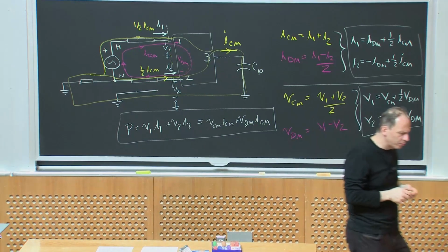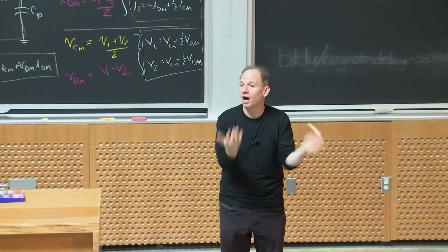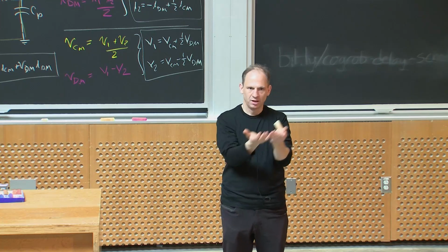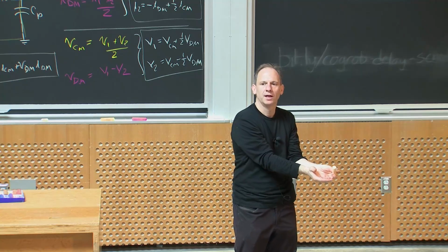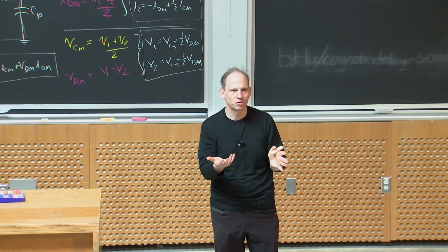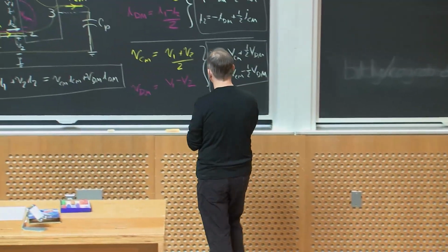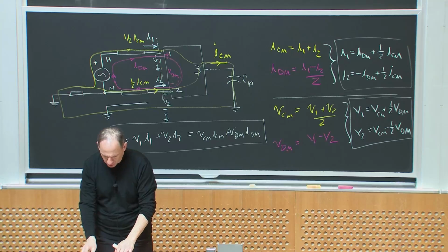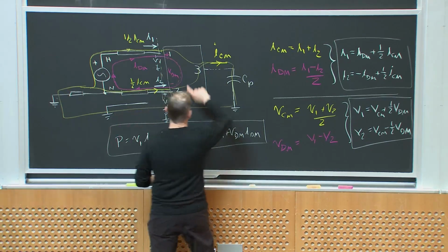But the other reason why people think about this decomposition of voltages and currents is because I tend to use different techniques to fix common mode noise and differential mode noise. Okay? And so decomposing it that way tells you what technique I should use to make a better filter. Okay? So let's think about this for a second. What might I do in a filter design? Well, let's go design a filter for this thing now.